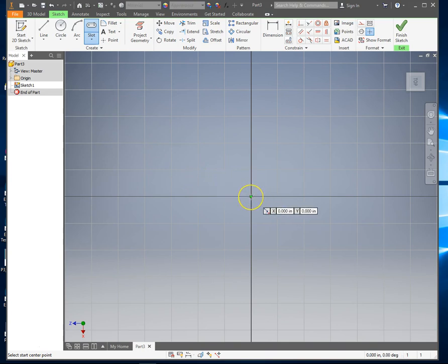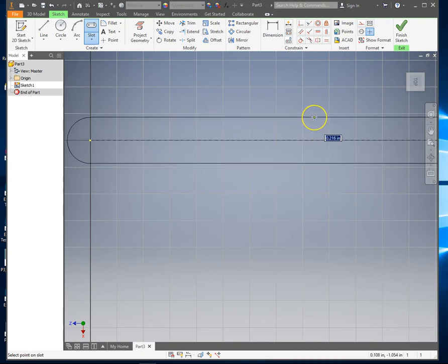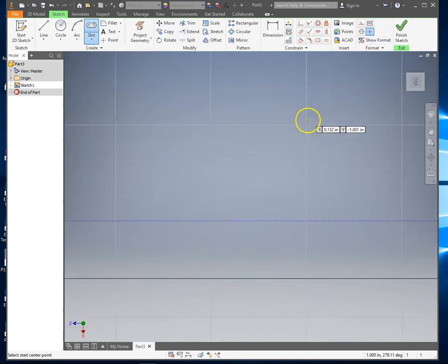So I'm going to specify one of my holes to be in the center. This other one goes out. I meant the center to be at the origin is what I meant. This other one, let's see, to the other center is 2.5. And then as I go this way, then I can put in my size this way, and it looks like the outer one has a 1-inch radius, which is going to be a 2-inch diameter. So I can draw that.